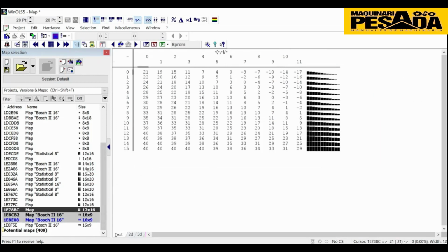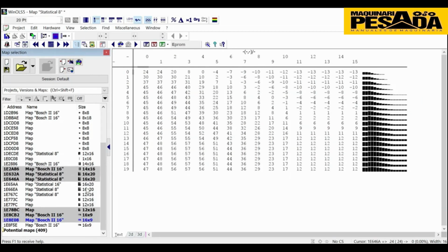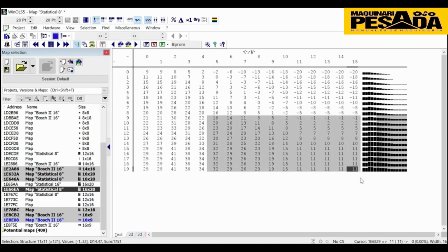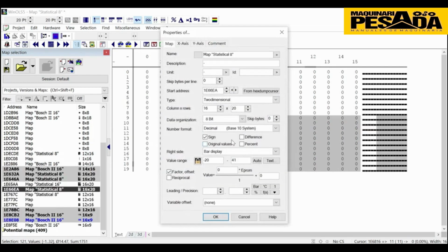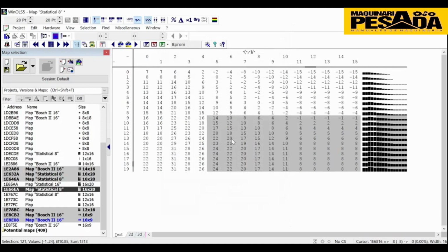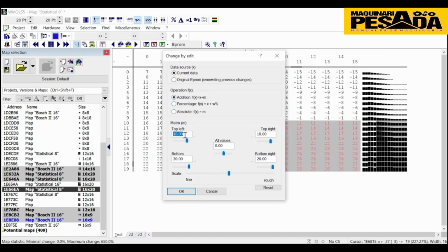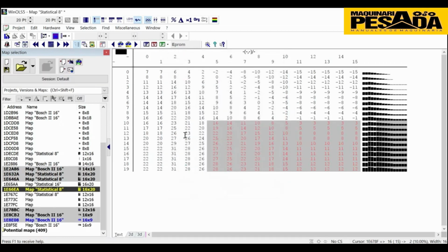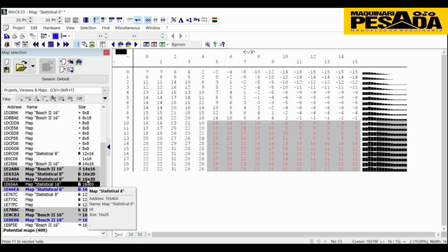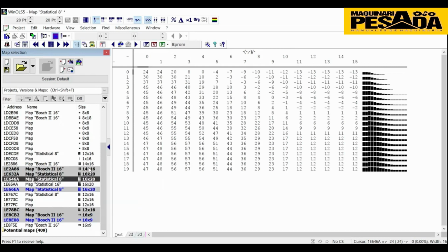About the spark advances that we have here, for example, these spark advances, you can increase here around 2 or 3 degrees, not 6 or 5 degrees, because too much advance in the GDI direct injection engine may have some problems. Then you can select here. We normally try to increase around something like that, 2 to 4, and you have to be careful about engine knocking, and you need to do the same for the others.